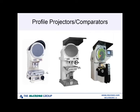There are two different configurations of profile projectors. The two here on the left are configured as vertical comparators. Again, you put your specimen here on the stage. You have 3 objectives here that look down onto the specimen, and the image is depicted here on the screen.